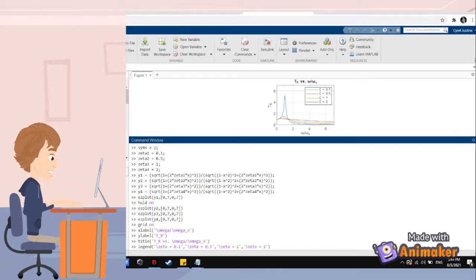It is desirable that the mountings have a low natural frequency in order to isolate the vibration source from the equipment platform, since the basic principle in vibration isolation is to make the natural frequency of the machine on its foundation as far below the excitation frequency as possible. In this way, low stiffness isolators will be effective to isolate the vibration source.